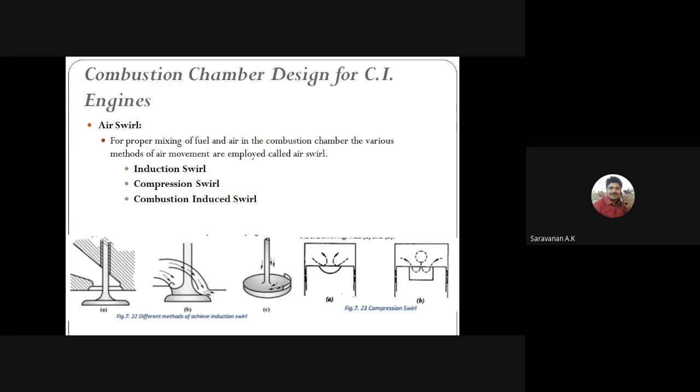The time available for the vaporization and mixing of fuel and air is very limited. So for better mixing and better combustion, air swirl is required. For better combustion, the atomization, vaporization, and proper mixing with the air are required in minimum time.